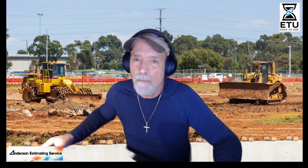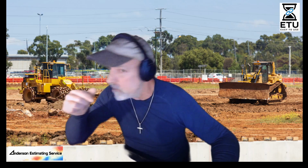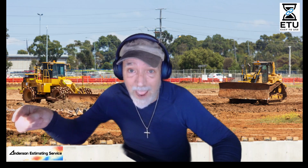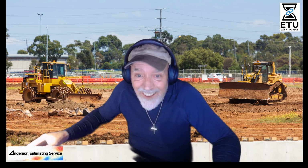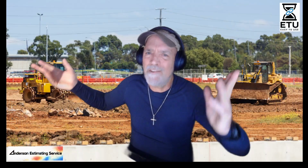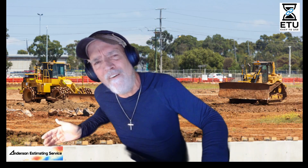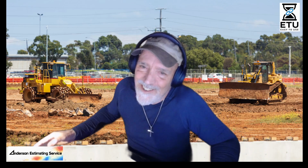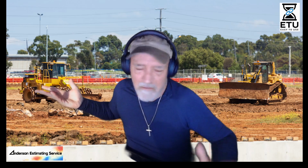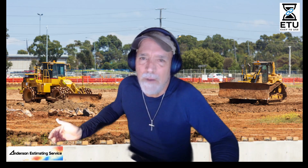107 yards. Now, if somebody had done this and built the original model and overbuilt the pads in their model, guess what? They would have imported 107 yards more. You're saying, it's only 100 yards, Alan. What the heck? What do I care about 100 yards? 100 yards at $25. Let's just say import or export is $25. That's $2,500.